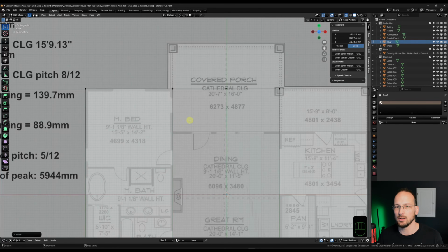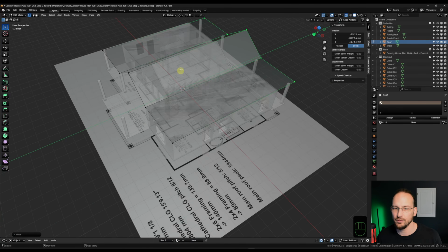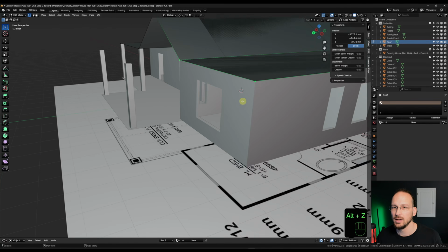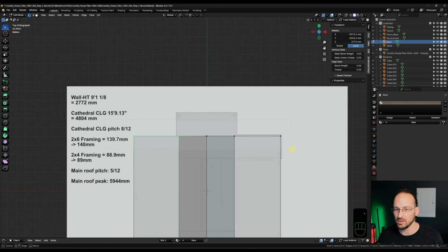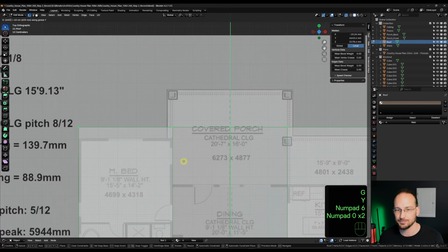And then the same thing on the back side. We're already on the outside wall here. And if we look at this end here, I'm going to go to X-ray mode for a sec. We don't have a porch here, so we have a big window, which means that overhang is supposed to provide some weather protection for the window and everything there too. So we're going to go with 600 millimeters on that side. So back into top view, select everything up here, GY 600.